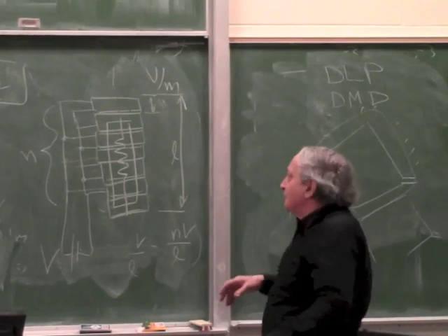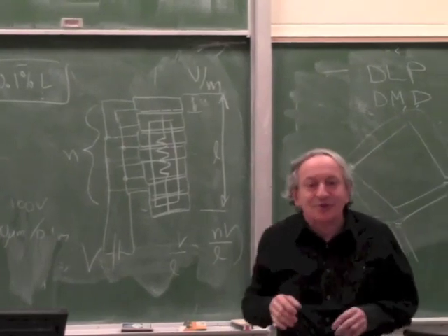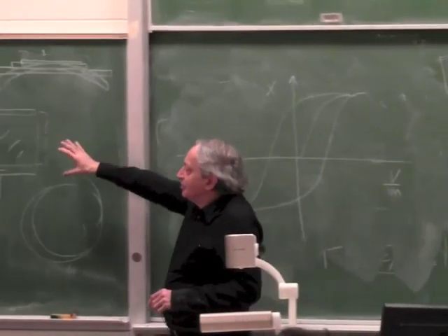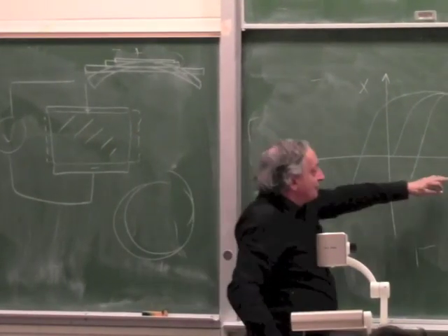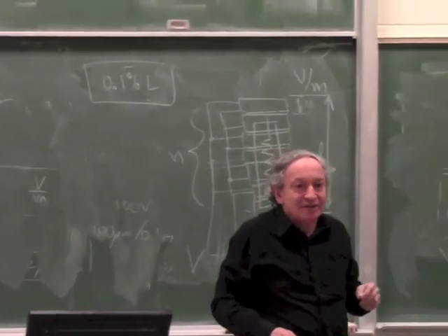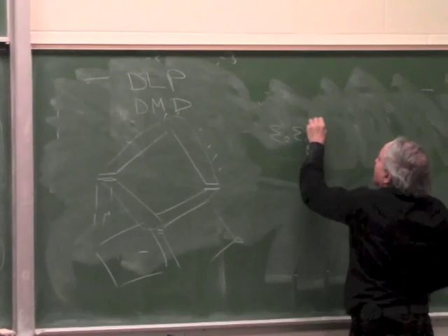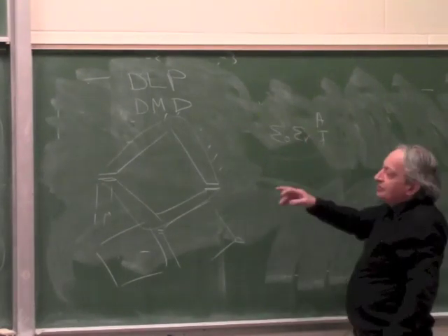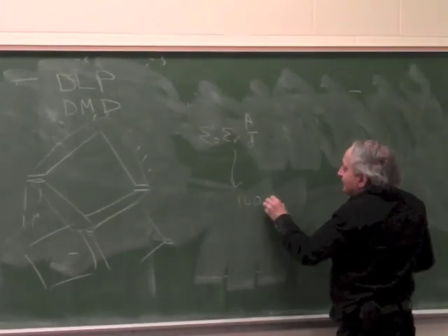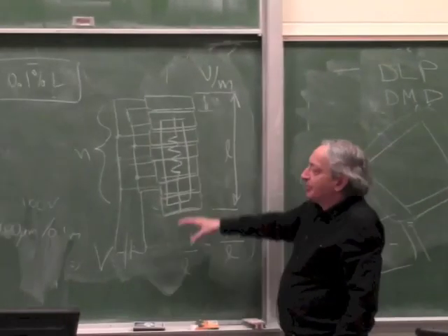Superficially, you would say that should be a very good actuator because I can move it very fast. There are no moving parts, but that's not so. It turns out the materials which have a high piezo coefficient, which is how much it moves per volt per meter, also have an enormously high epsilon r. Like we said, capacitance is epsilon 0, epsilon r, A over D. Now the materials which have the best piezo property have an epsilon r on the order of 100,000. Okay? That means that a stack like this presents a huge capacitance.